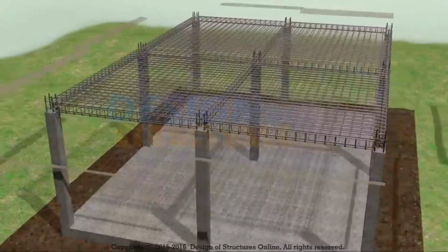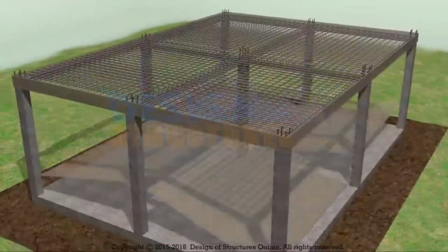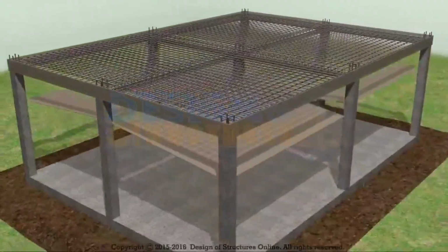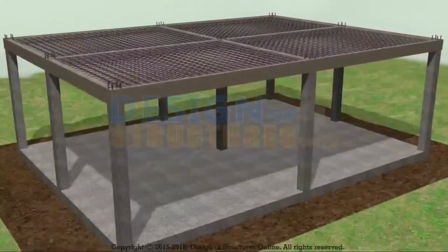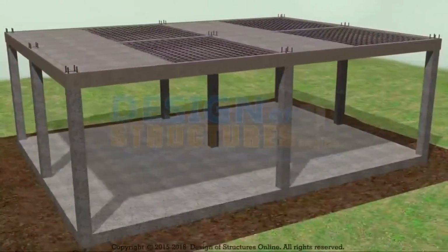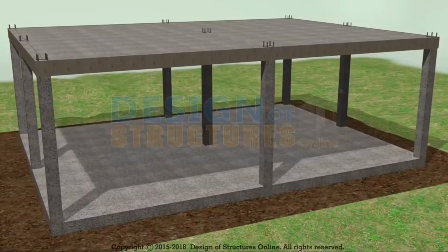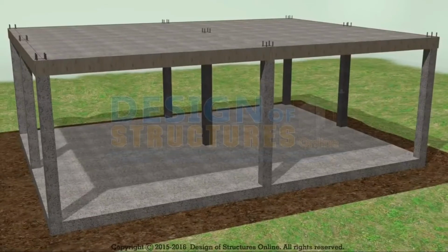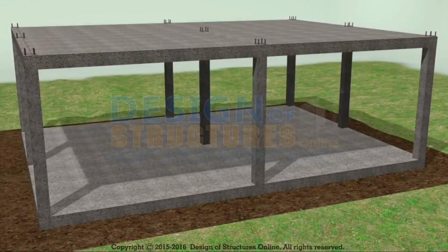Slab shuttering. Beam bottom is first laid on the column and then slab shuttering is laid. Beam and slab levels should be maintained as per drawing. Slab concreting. After the concreting of column, beam and slab concreting shall start monolithically. The top of floor beam and slab shall be maintained as per levels. Slab shuttering removal. Special attention is required for